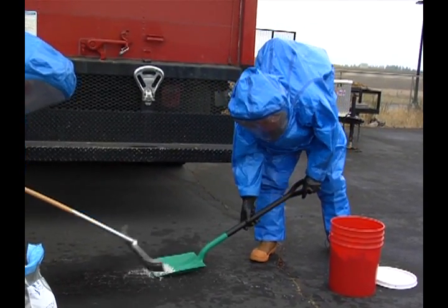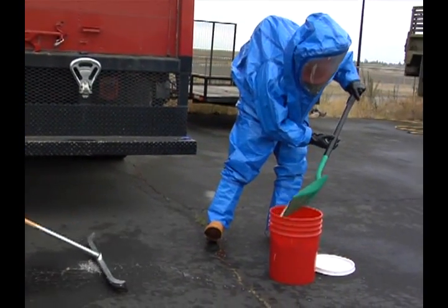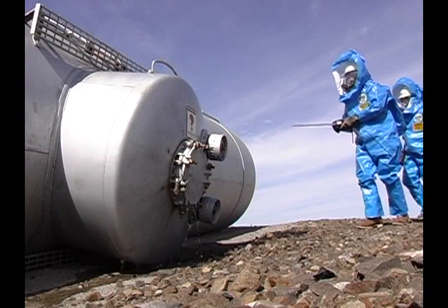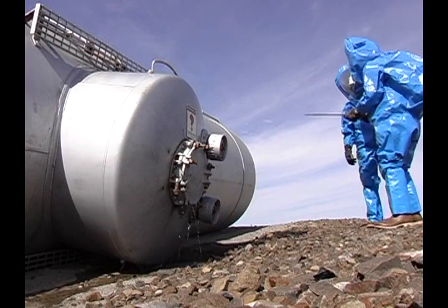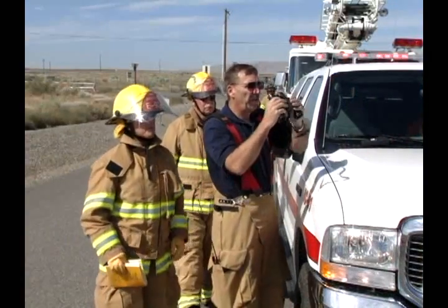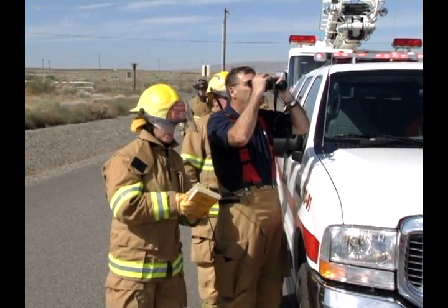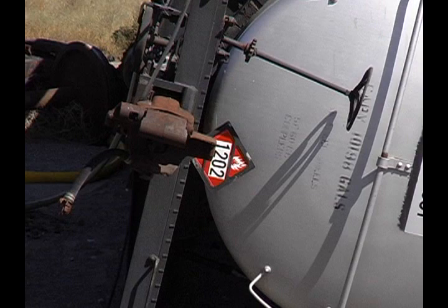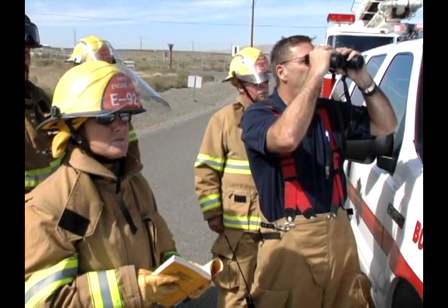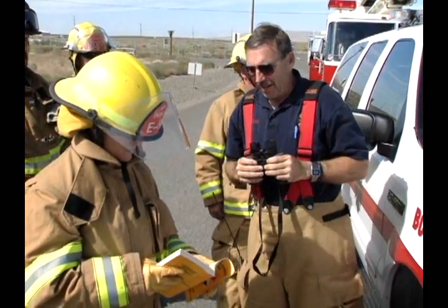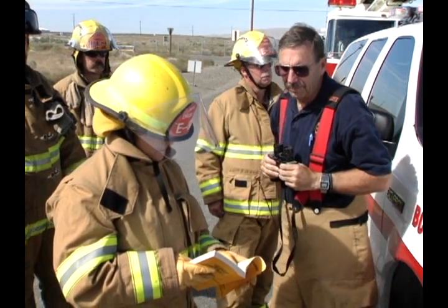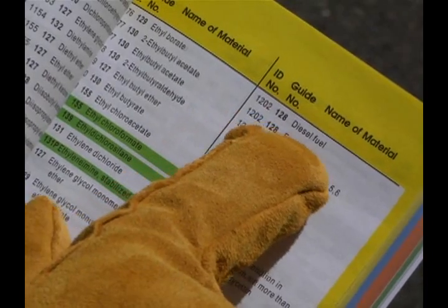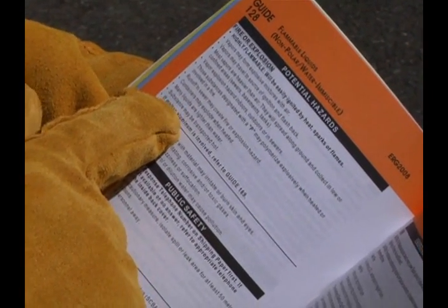Safety rules are especially important in spill control operations because responders are usually heavily exposed to hazardous materials. We got an overturned rail car. As with all hazardous materials incidents, identify the product before you proceed. It is essential to know what you are confining so you can make decisions about personal protective equipment and spill control procedures. 1202. Fuel oil, diesel fuel. You should know the chemical and physical properties of the product as well as its name.